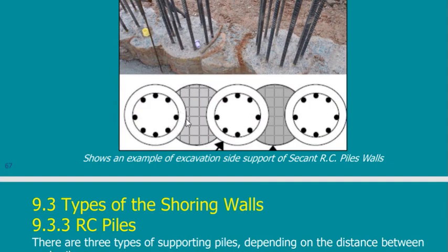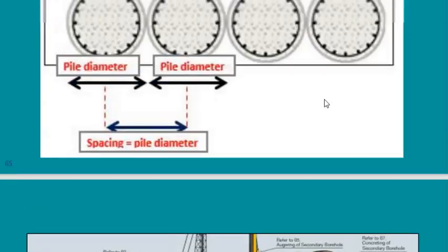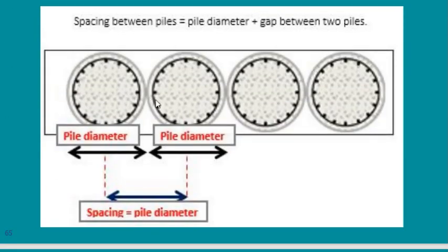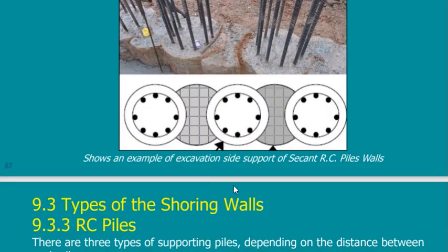These are called bentonite piles. They are helping piles. They are not the main piles, but they are used to prevent water. You remember my problem here was that in tangent pile they are touching, so any minor construction fault will result in water passing. So I need to put a plug here to prevent water from passing. This is exactly what I've done here.